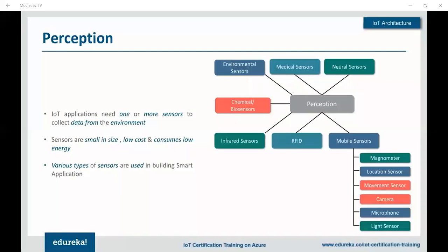A near RFID reader uses a coil through which we actually pass AC current and generate a magnetic field. Now, when we generate a magnetic field, anything that comes in its vicinity registers with respect to it. Now, when I talk about a far RFID, it basically is a dipole antenna in a reader. Now, this again propagates in electromagnetic waves, and tags themselves also have a dipole antenna. Again, these are used in various applications that are out there.